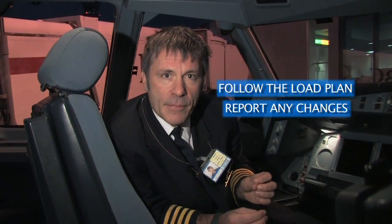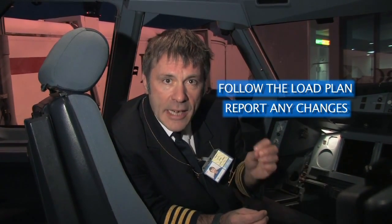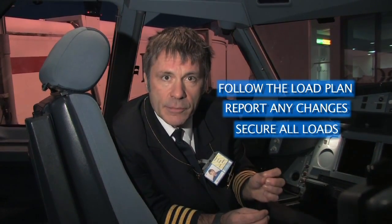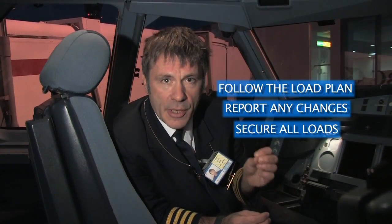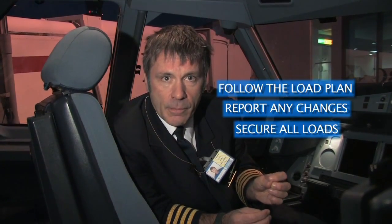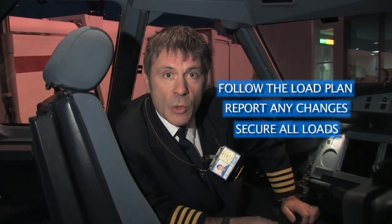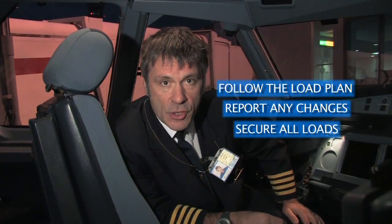And thirdly, and very importantly, any loads you do put on an aircraft should be secure. Make sure the load is secure. Make sure the locks are in place. Make sure it's strapped down and it will not move under the stresses and strains of flight.